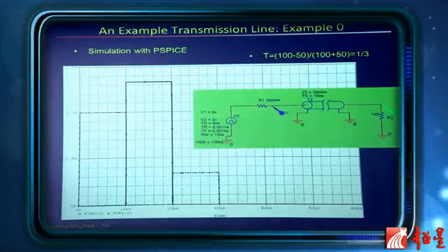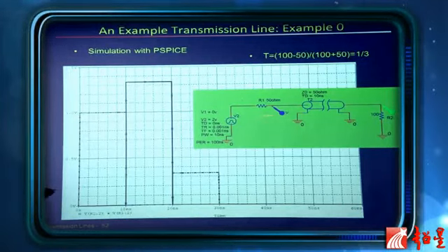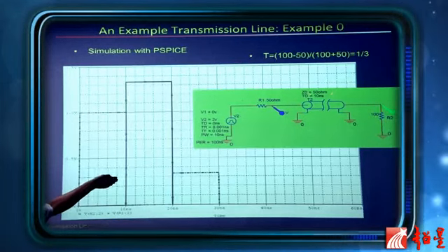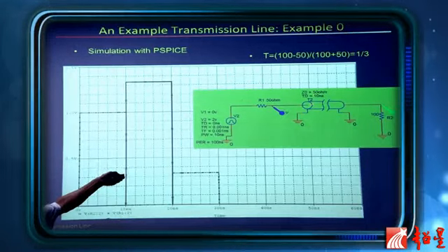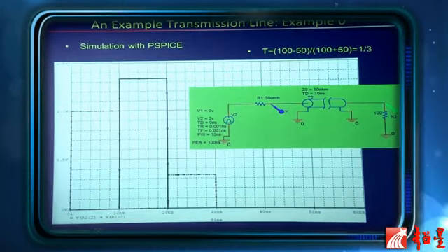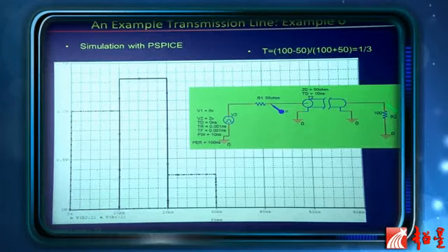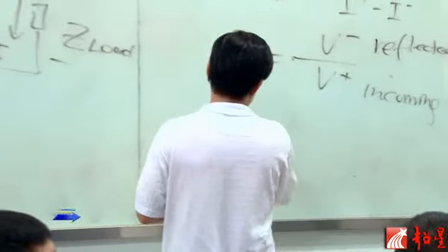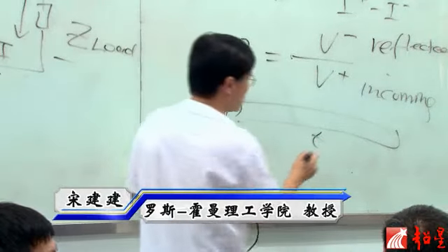Okay, all right. Now, this is a SPICE simulation. Assuming this is a transmission line, the transmission line here is described with two parameters: the characteristic impedance and the length of the line. Of course, from this you can find out the other parameters. If I know the length of the line in terms of time, the propagation time is T d.